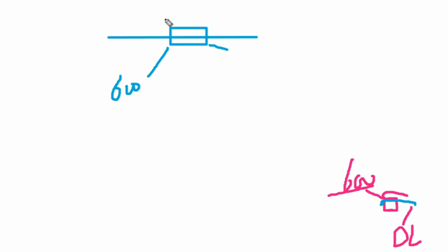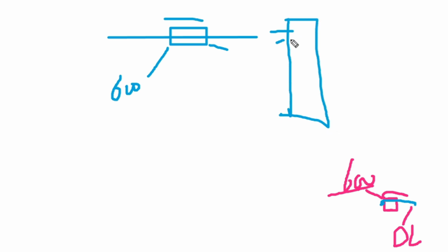You can connect a jumper from both ends. After that you can measure on the connector, and if you get a value here, that means your job is done. Your first step is complete. Most probably your earphone has been repaired.